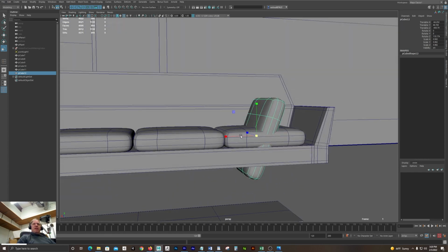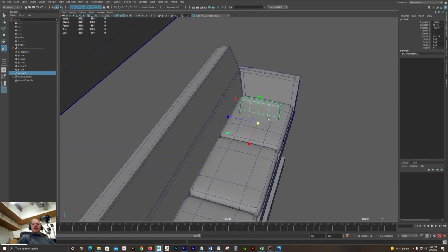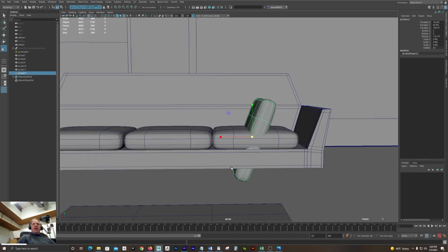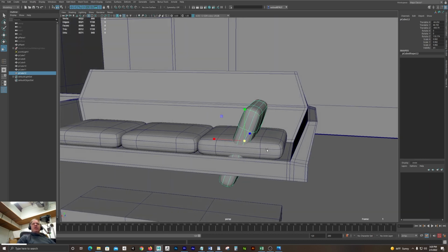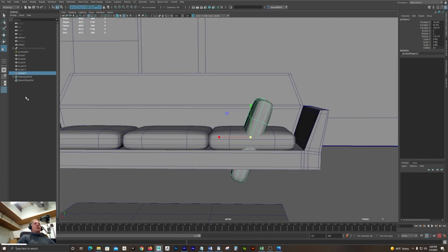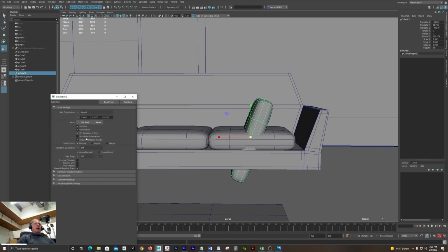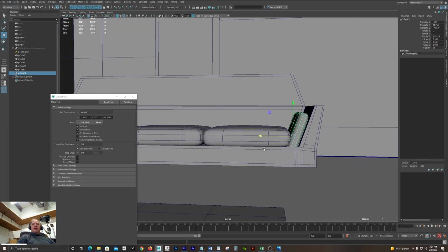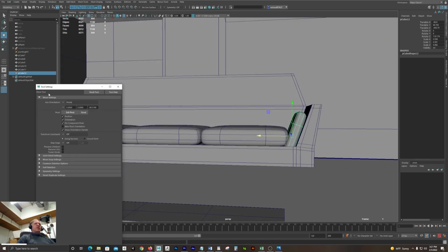I don't want to scale it from the center because that's scaling it in all axes. I only want to scale it in Y and in X, but I only want to scale it in the object's X or Y. So I'm going to go over to the toolbar over here. This is the scale tool. I double click on it, and where it says world, I shift to object, and you can see now it's got the object orientation, axis orientation. And for my move tool, which its settings popped up when I shifted tools, set that to object as well.